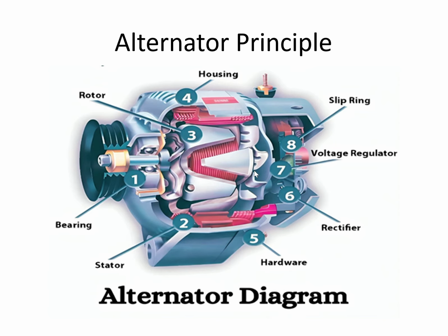So this is the motor hardware part. The slip ring is nothing but three separate rings. If it is a single phase alternator, there will be two slip rings. The slip rings enable the communication between the external source and the internal part of the machine, that is the winding of the machine. So this is about the construction of the alternator.